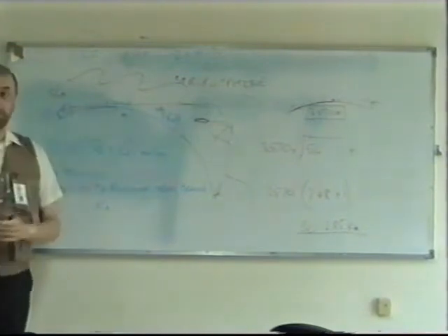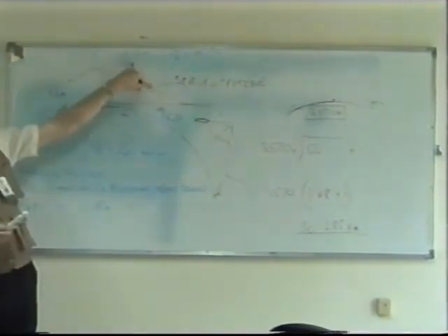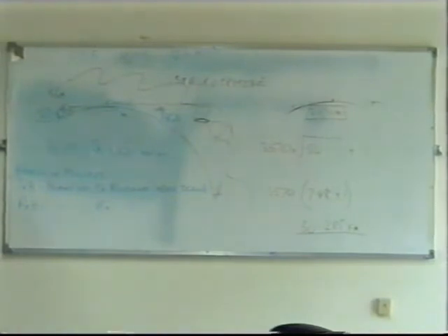Of course, this doesn't tell you your coverage. This just tells you your theoretical range. If you're on UHF, for example, remember what happens when a wave hits a building. Some of it will be reflected, a lot of it will be absorbed at UHF, and very little gets through. So although you might be able to talk to a car 30 kilometers away, a car a few streets down, just a kilometer or two away, you might not be able to talk to because of the buildings in between. So it doesn't necessarily give you all the answers. You've got to consider coverage as well.